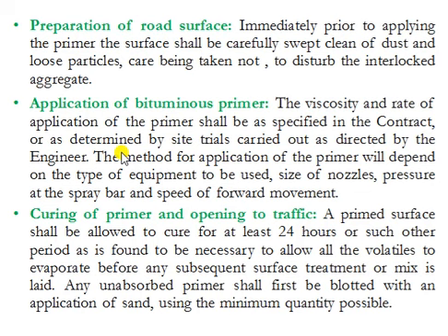If there is any unabsorbed primer, he should rectify that, and for that place he should use a fine aggregate. The quantity of fine aggregate used in the place of unabsorbed primer should be minimum, and